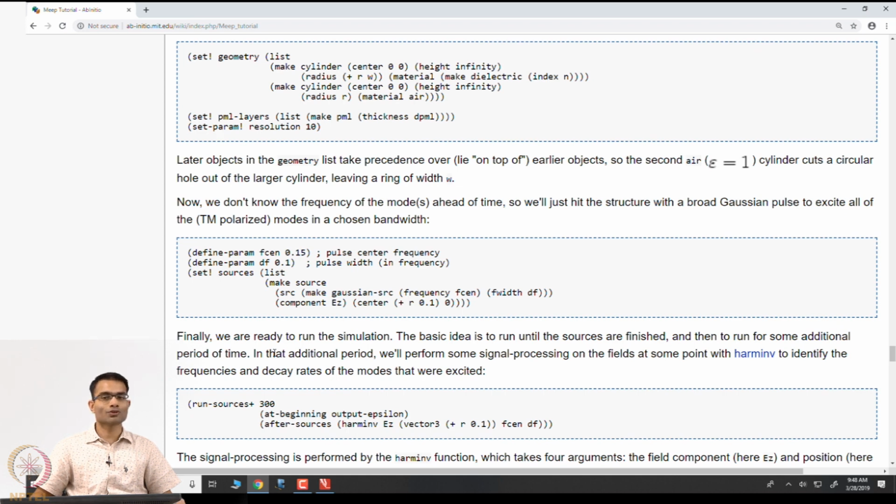So, he is saying go around the structure and find out where the nodes are. That is a very crude way. Is there a smarter way? Find out the Fourier transform. I have time domain data, calculate the Fourier transform. That is a much smarter way. It will give me not just the frequency peaks, but also how resonant they are, how sharp they are, right.